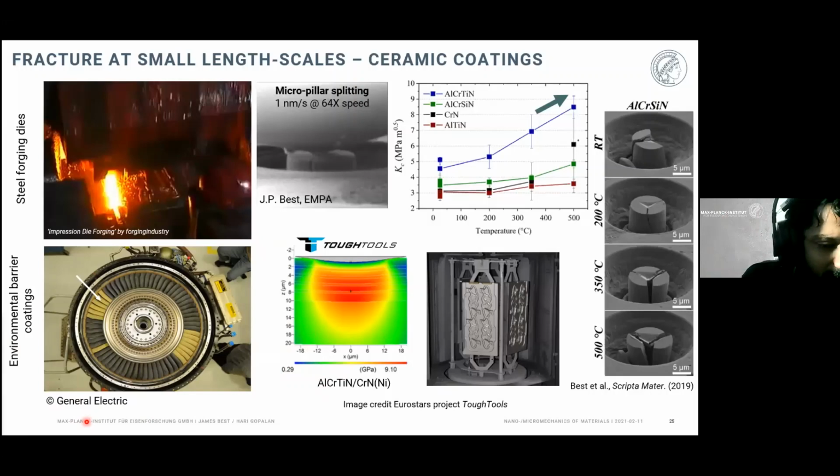And one of the things that is relevant here is we want to have coatings which can protect this silicon carbide at elevated temperature, where it is especially susceptible to water vapor corrosion. So we want coatings which are resistant to a combination of temperature, water vapor, and aggressive media. So the tests that you nicely showed are useful to quantify whether these things can put up with that extreme condition.